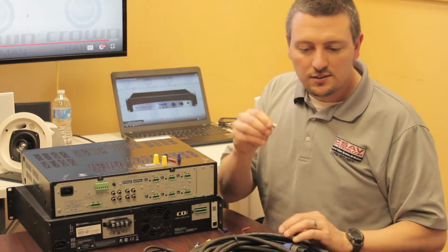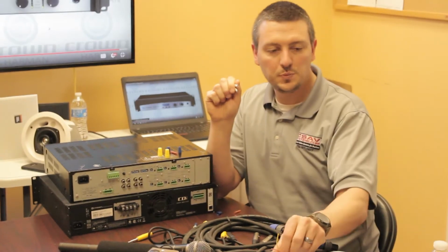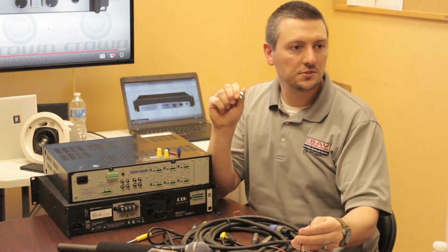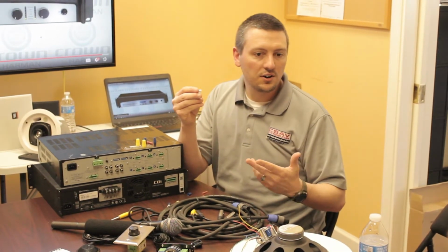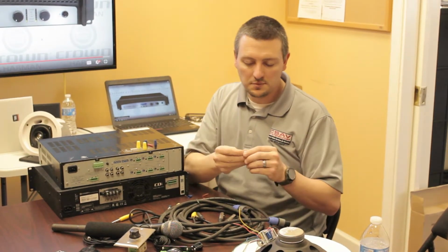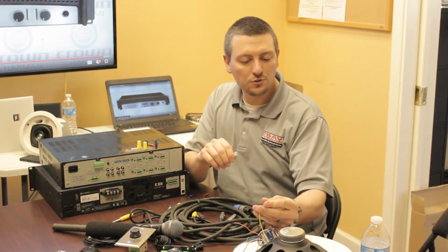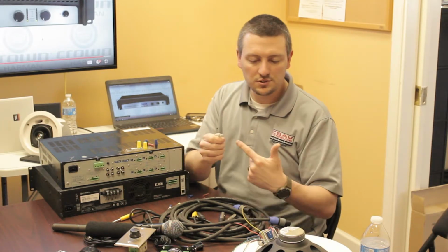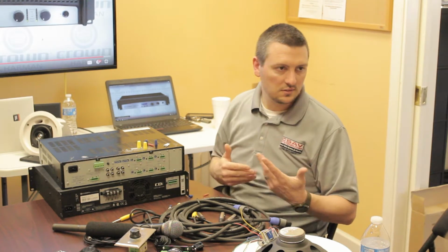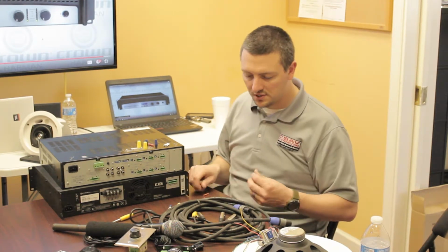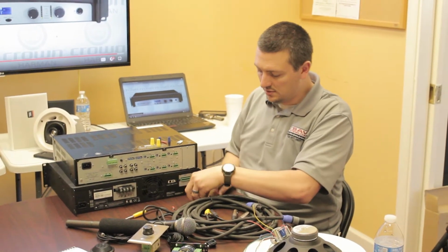These guys, I typically wouldn't use for speakers or anything that's passing a lot of voltage. If you're splicing RS-232, IR, stuff like that, this would be the typical mode. If it's something small, only passing a couple watts through here, these are fine. But I wouldn't use these for anything that's sending high voltage through. I always tend to use the wire nuts, twisting those things together.